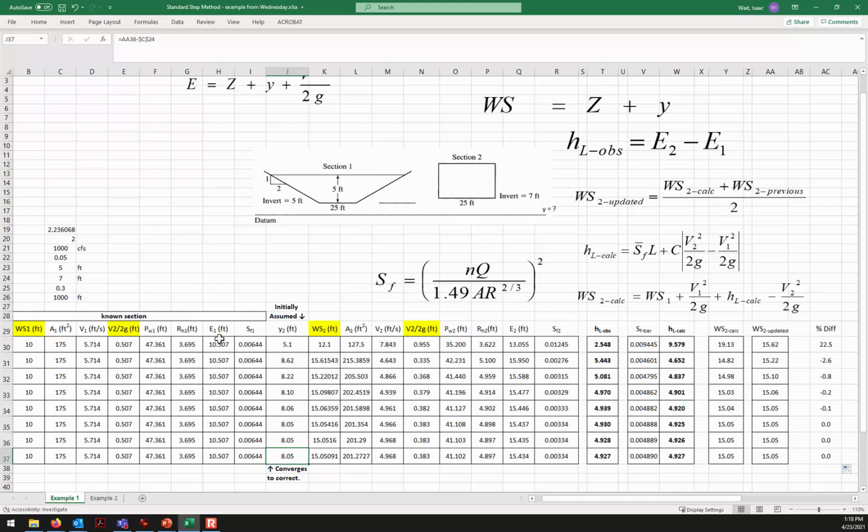breaking up a channel that's gradually getting wider and narrower and the slopes are changing. Anytime there's an adjustment in the channel, you just chop it up into lots of little slices. And the more slices you've got, the more accurate your model is going to be, because remember, what we're doing is we're approximating a curve with a line.